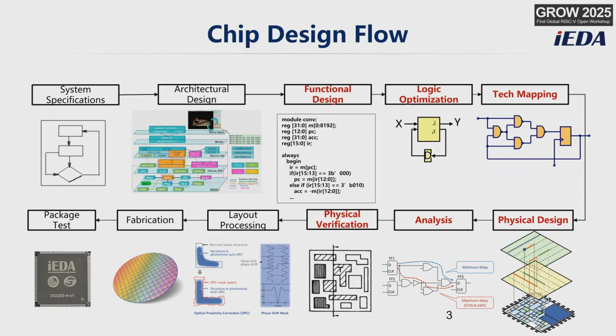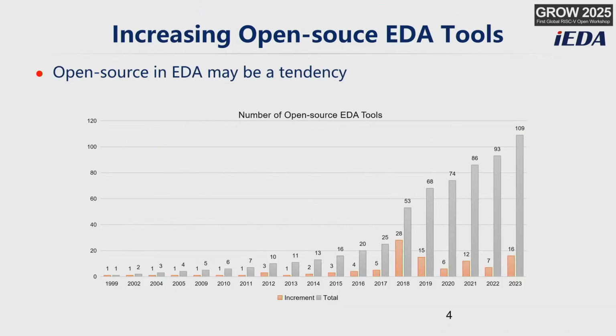This is a typical digital chip design flow, starting from the system specification to the final package and test. The EDA project involves the internal steps with the red letters, including logic synthesis, physical design, analysis, and physical verification.